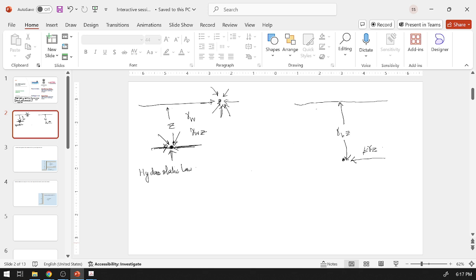It is in proportion to the vertical stress, and we can say that sigma horizontal is directly proportional to sigma vertical, or we can say that sigma horizontal is equal to K times sigma vertical, where K is a constant of proportionality. The value of this constant will depend on the state of stress that the soil is in. Is it in active stress, passive stress? Is it at rest? So that is what we will basically be studying in this topic. That is the first point for you to visualize easily, the lateral stress at a point.